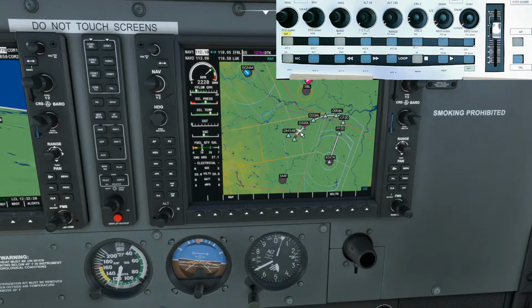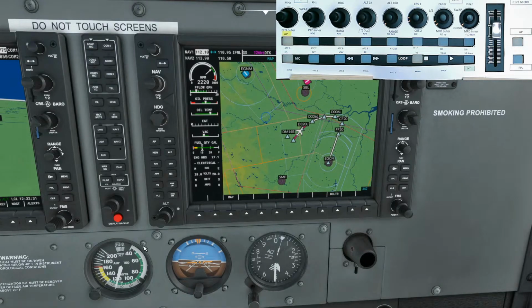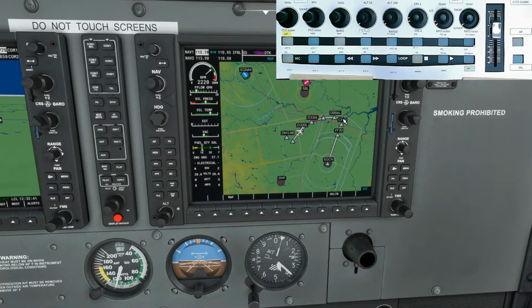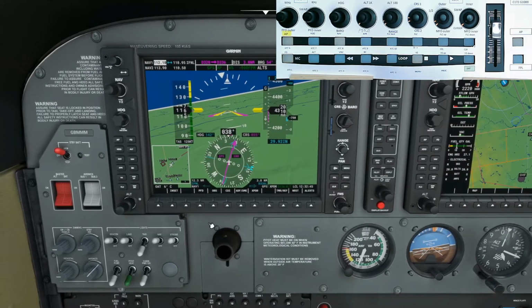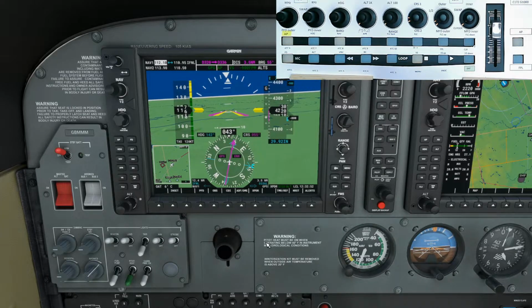So what we're flying here is called a DME arc. There's a beacon here, and you can fly that just with the DME equipment, and it will give you a distance that we're flying away from that arc. It's probably an 11 mile arc on this one. And all you're doing is flying and turning, and trying to keep a regular distance away until you reach the localiser, and then fly down the localiser. Oh, it's a 12 mile DME arc.